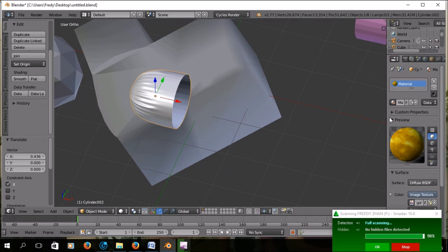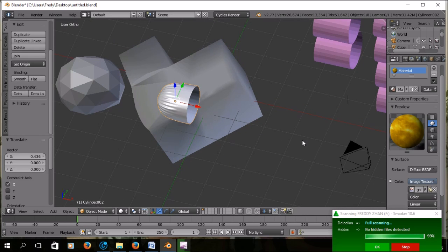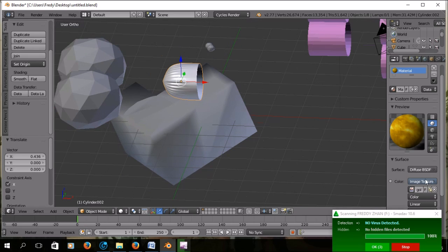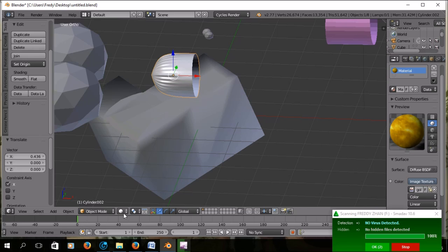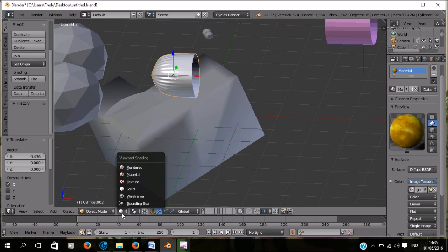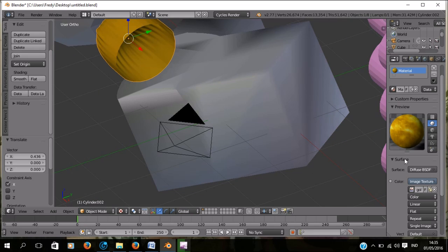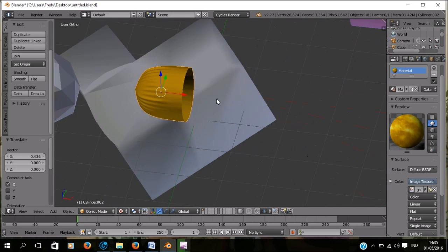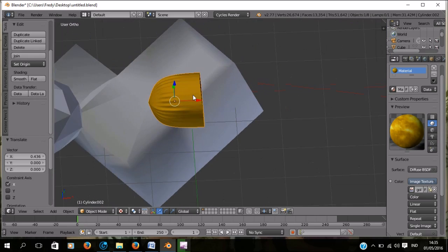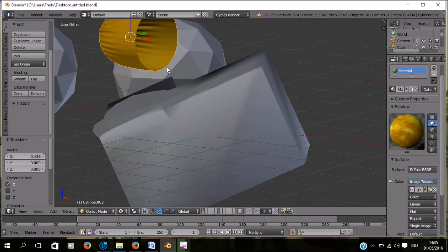But when there's no color like this from your picture, well, there's something wrong on your computer. Okay. Well, to add a picture, you simply click on the right side of the object node and click viewport shading texture. Whoa, why does it show a yellow color? And this is also yellow. It's like camouflage. Well, as I know, version 2.77 works like this, but in another version it won't change the color. Okay, so next, it's still not changing the color.